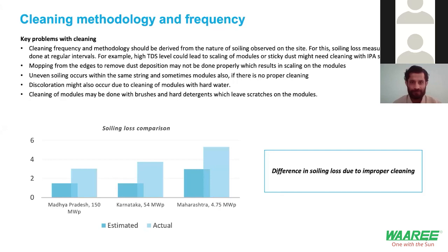So that can be properly incorporated over there, because later on, once there is an as-built PV and the plant is under operation and not performing well, then they ask us to come in, saying the as-built PV is this, but the performance is this. And then you find that the soiling assumption was 1% in the PV during the construction phase, during the design engineering phase, but actually on site it is 1.5 or 2%. So that is a big learning that we have made over time.